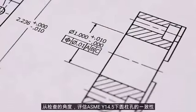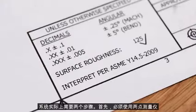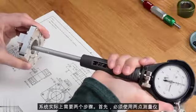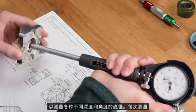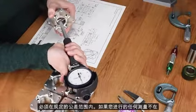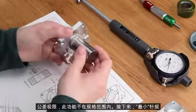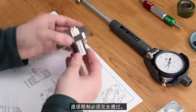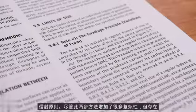From an inspection standpoint, assessing conformance of a cylindrical bore under the ASME Y14.5 system actually requires 2 steps. First, a 2-point measuring instrument must be used to measure the diameter at a variety of different depths and angles. Every measurement taken must lie within the stated tolerances. If any measurement you take is outside of the tolerance limits, the feature is not in spec. Next, a go pin gauge for the minimum diameter limit must completely pass. In GD&T classes and books, this second step is sometimes referred to as Rule 1, or the envelope principle.